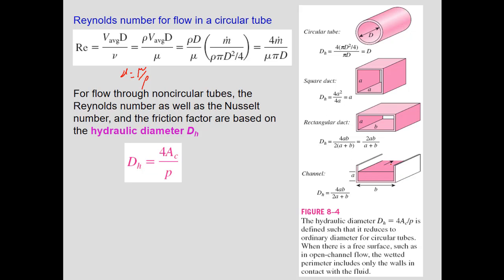Here we don't have any duct on the open side, so we don't have any friction there, and we don't have any heat transfer between the duct and the fluid. So in our consideration we should ignore that. So the area is again the same, AB, but the perimeter P is different. It is only this part, 2A plus B.